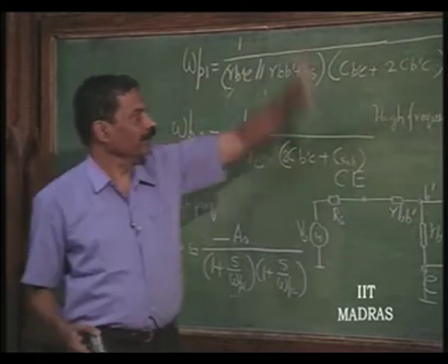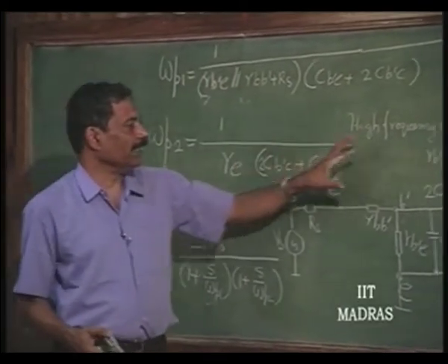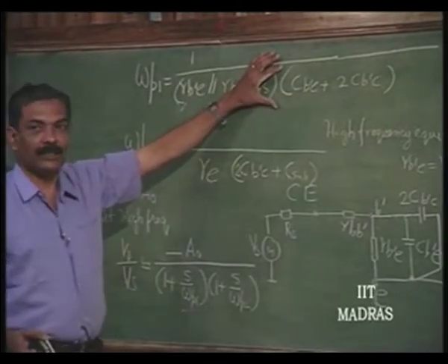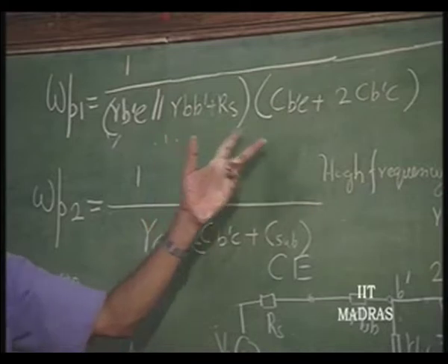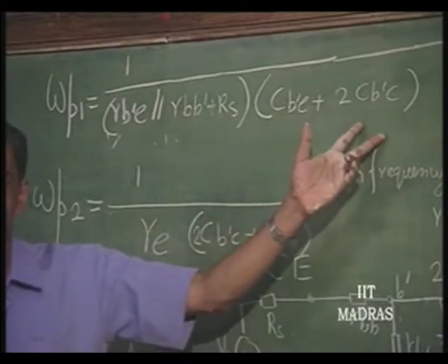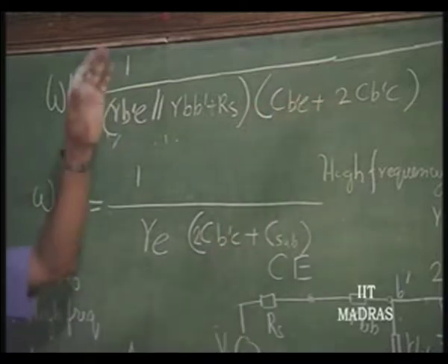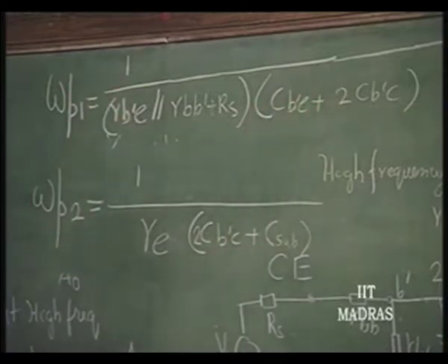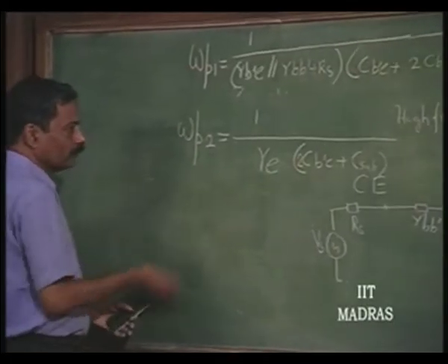So, this goes very high, this is the intermediate pole. So, this is very high, this is still perhaps dominant, because this resistance is not very small, this capacitance is quite small, but compared to this it is still large, right, but it has been reduced from the earlier value, and ultimately now it has a third pole.